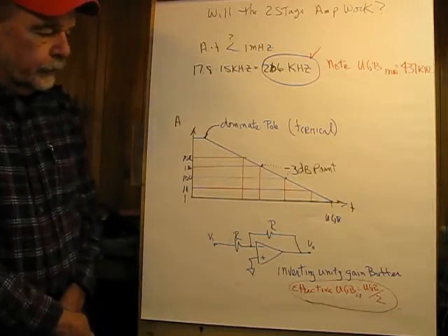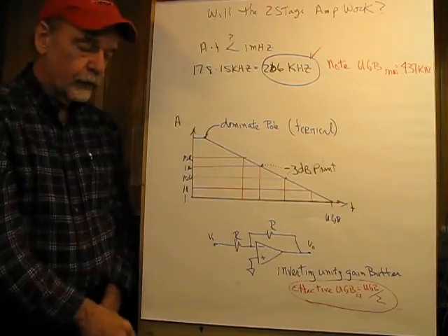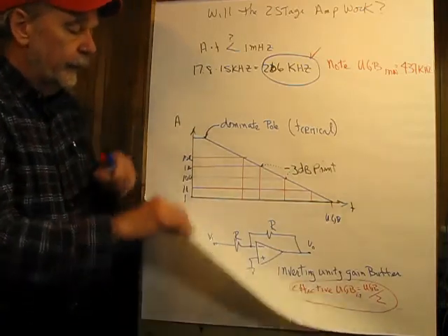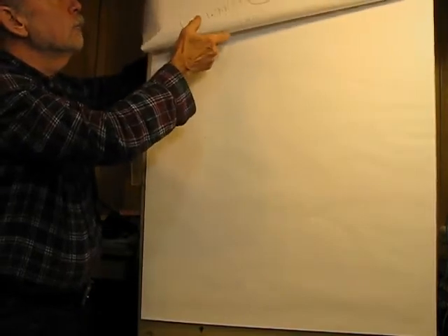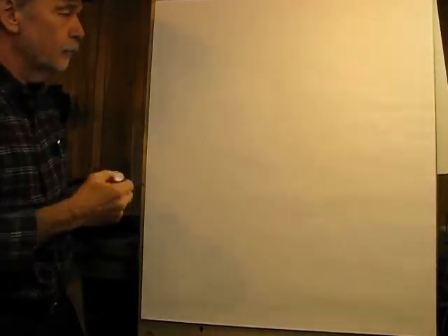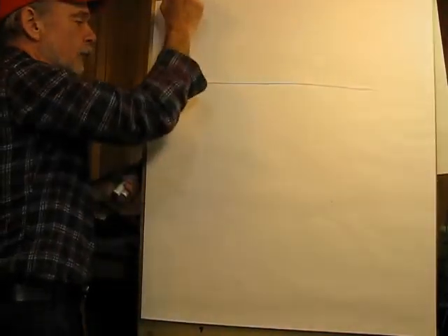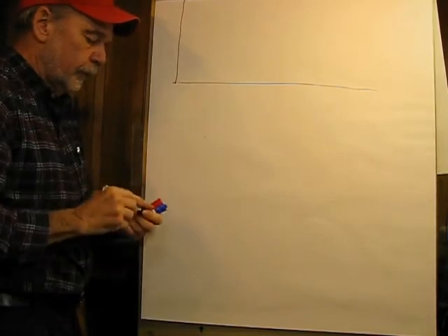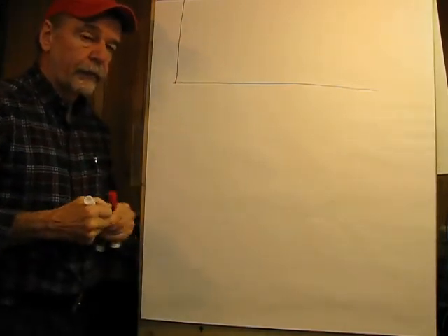So in conclusion, it'd probably be a better idea to look for a more contemporary operational amplifier. And with gains like that, in the 316 range, looking at an uncompensated op-amp, the NE5534 comes to mind.